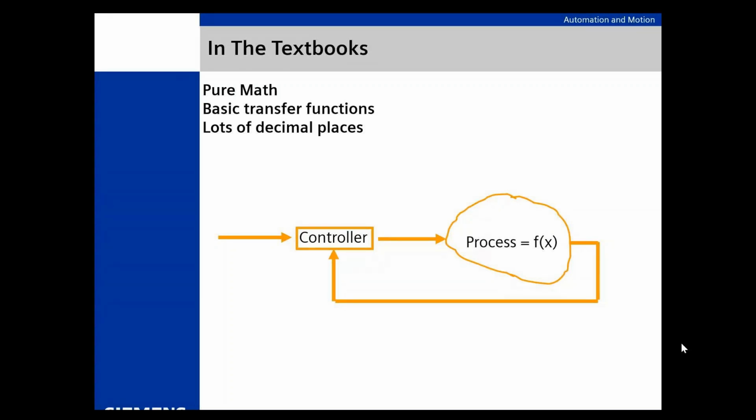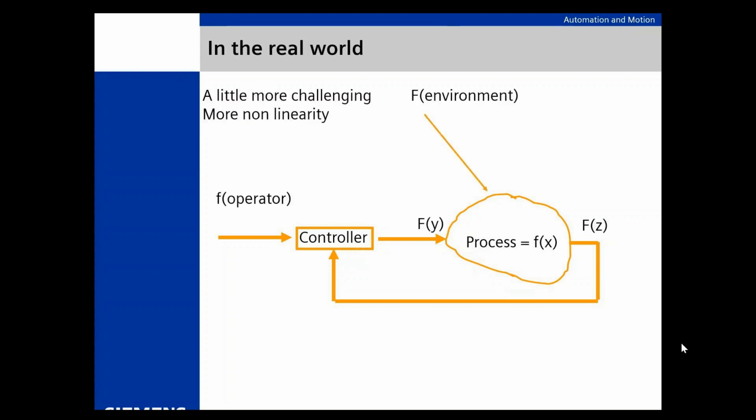We all know that. What's next? Well, I've got to deal with the environment. I've got to deal with flows that change and pressures that change and temperatures that change and lag in the system. My controller tells a valve to open. That's not instantaneous. A valve has to take some time to open. It takes time for a flow meter to respond to that flow. And people say, well, that's not very much time, but that's true, but it's there. And it has to be dealt with.